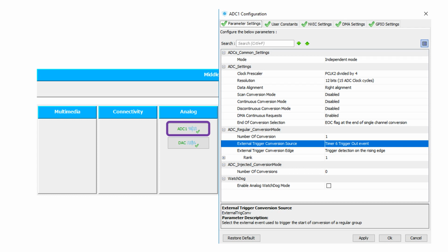So let's say we put something in the while(1) loop in main. The CPU could be executing what's in the while(1) loop in main without having to worry about grabbing information from the ADC register into the buffer, or from the buffer into the DAC. What this basically means is that we'll get a significant boost in the overall performance of our system. And that's what we want, because we want to be spending more time processing our signal than in the auxiliary task of grabbing our data from the input and sending our data towards the output from the ADC and the DAC channels. So we've offloaded that to the DMA.